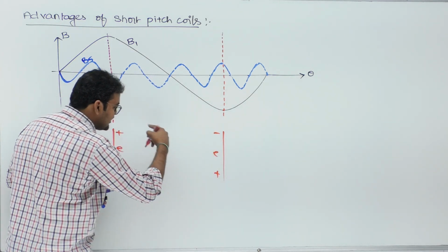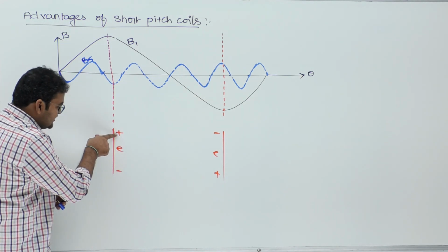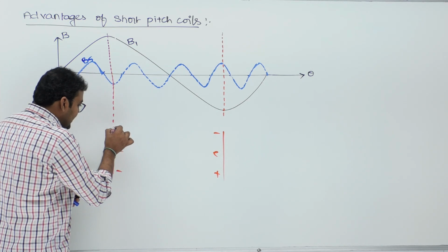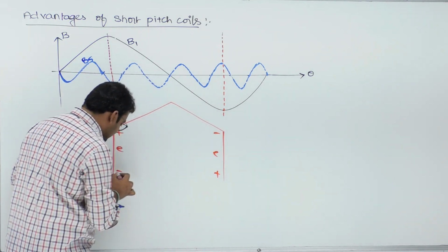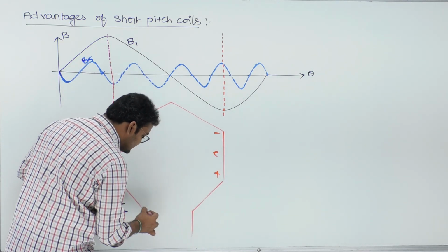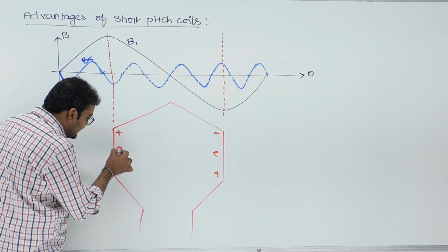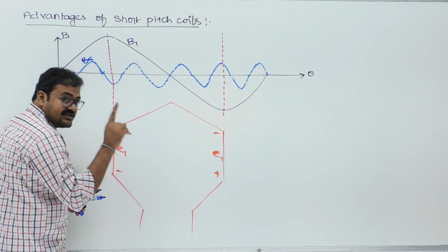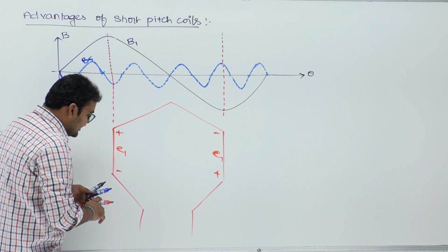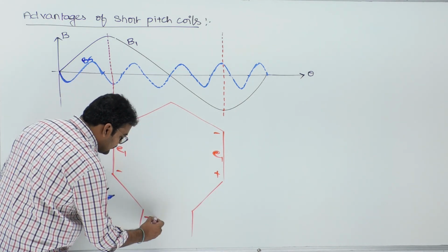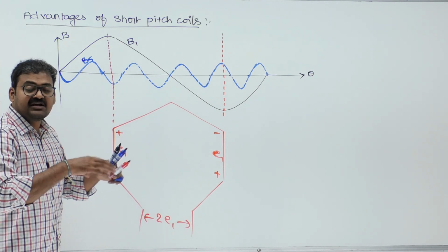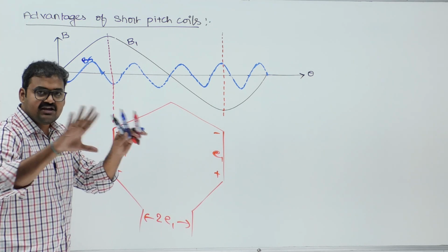You see the voltage polarity representation: plus minus positive voltage, minus plus negative voltage. Now these two are connected to each other. Therefore, you tell me what is the resultant fundamental voltage. Let us say E1, where 1 indicates the first harmonic, the fundamental. Can you tell me the resultant voltage is equal to 2E1. Okay, that means both voltages are adding. Fundamental voltages are added, very clear.